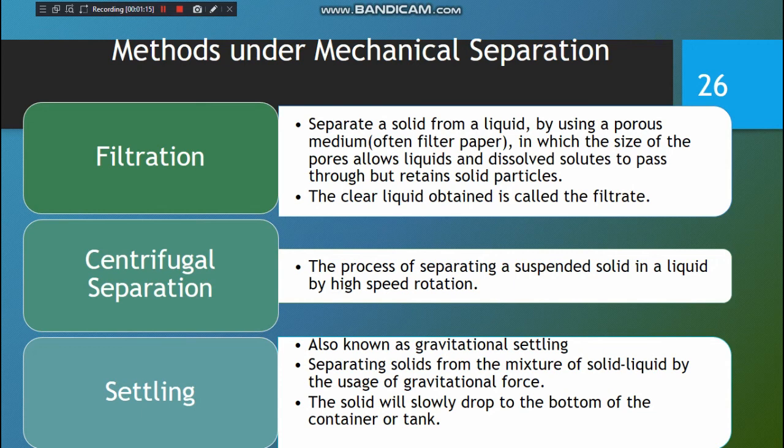By referring to the statement regarding mechanical separation, it can be understood that mechanical physical forces such as gravitational, centrifugal, mechanical, as well as kinetic forces are applied to solids, liquids, or mixtures of both in order to cause separation of the desired product. In order to achieve mechanical separation, the specific methods used are listed in the slide: the filtration process, the centrifugal separation process, as well as settling or sedimentation, and centrifugal filtration.